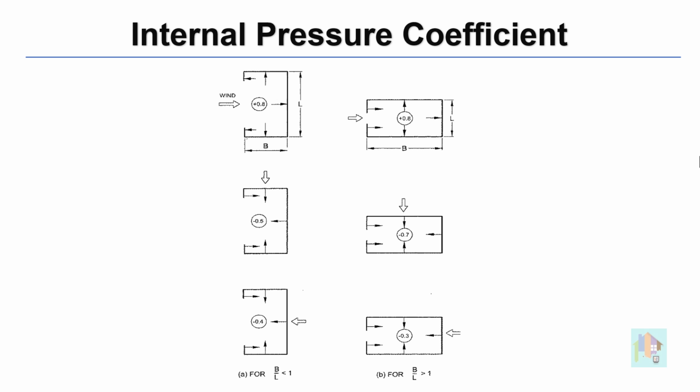For example, consider figure 2, which indicates the possible direction of internal load based on the wind direction. If wind acts from the positive x direction, it enters the structure through the opening and all walls are subjected to outward pressure, whereas for z direction wind, there is no opening, so wind can't enter inside directly, but there will be loss of internal pressure due to the opening. Hence, wind load due to internal pressure is changed to suction.